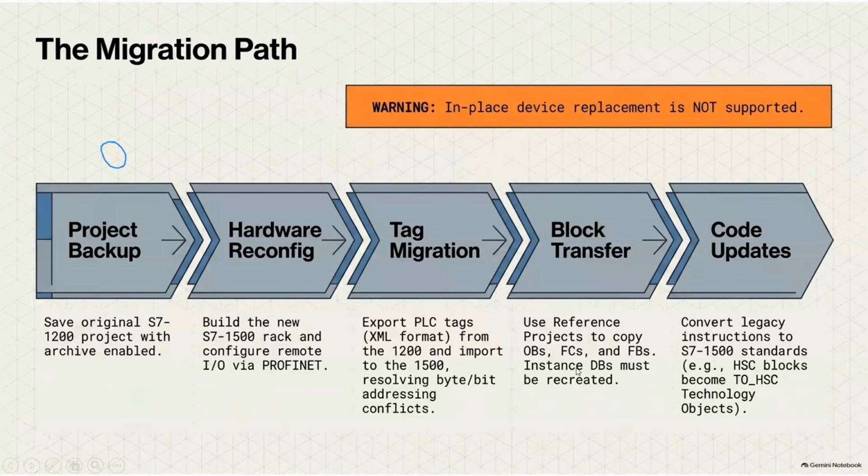It is very easy now whenever you use this S7-1500. Universally, it creates a set of tags. You only need to pull the tag or copy the tag and paste it at the IO port or in the SCADA. If you are defining it in the SCADA for the on button, you have to copy and paste the tag name directly. But for S7-1200, it is not in such a way. For each and every tag, you have to name the tag, and assign the tag in all the locations.